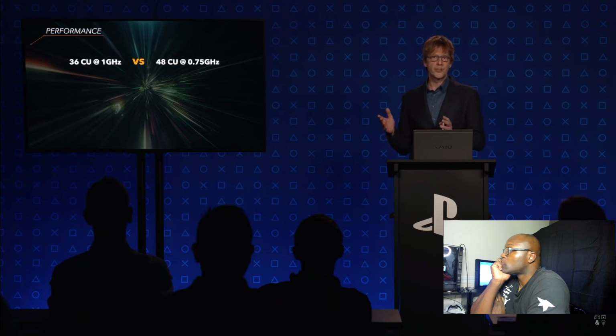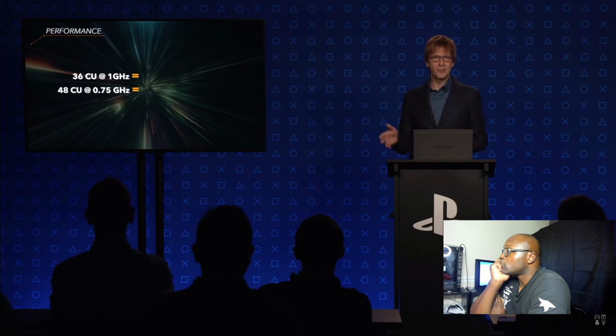The chip has a cost, and there's a cost for whatever we use to supply that chip with power and to cool it. In general, I like running the GPU at higher frequency. Let me show you why. Here's two possible configurations for a GPU roughly of the level of the PlayStation 4 Pro. This is a thought experiment. Don't take these configurations too seriously. If you just calculate teraflops, you get the same number.